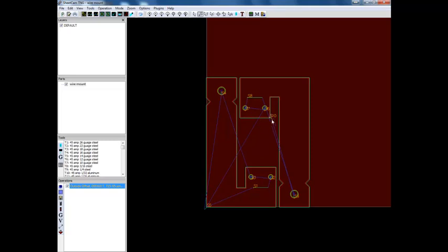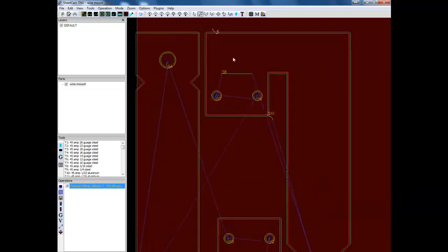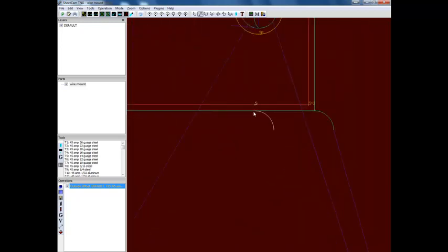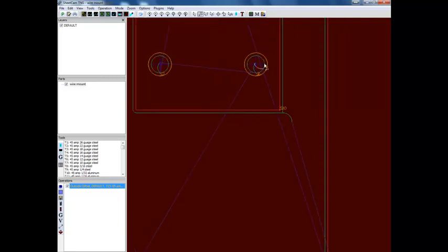The reason being is when you move a start point, the distance between where you can move it is the corner snap distance. And so this allows you to move very small distances. You can see it's kind of bouncing along there. As I move it, it's snapping to different distances. The smaller that distance, the more precision you have in placing your lead-ins.